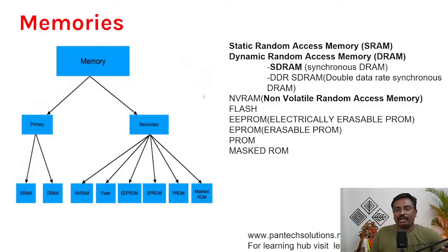If you have a lot of variables, for example in a complex image processing application with a lot of coefficients, you need a lot of dynamic random access memory, DDR SDRAM, to process those variables. And when you have more stacks, you have to choose the right memory with the right size when you design an embedded system. Otherwise, if you have not allocated sufficient space for the stack, it may cause a stack overflow. So the memory calculation has to be done.